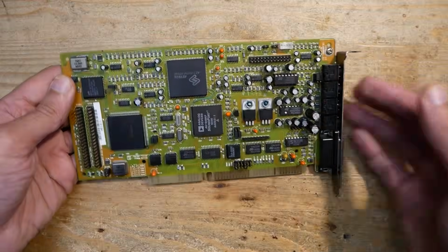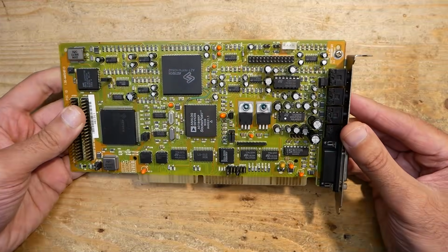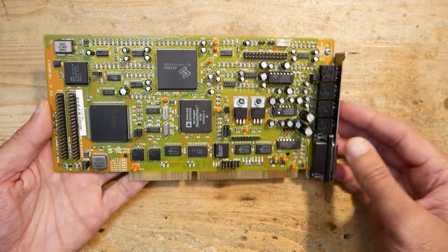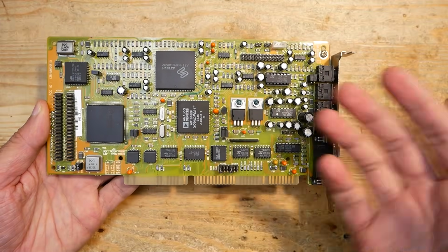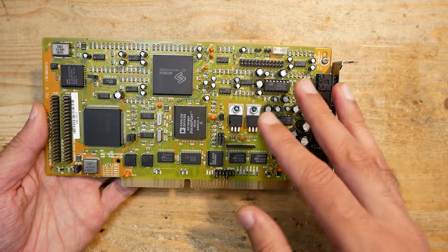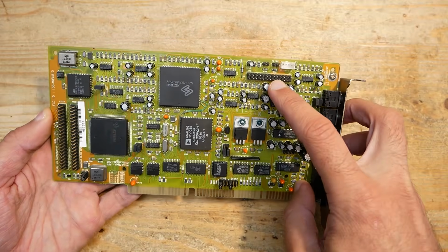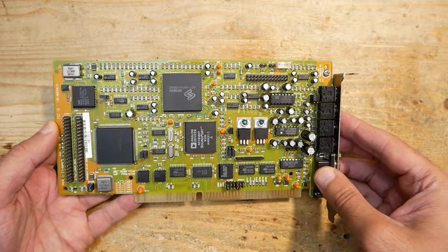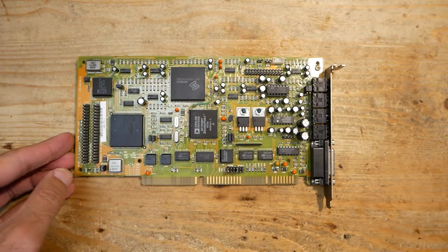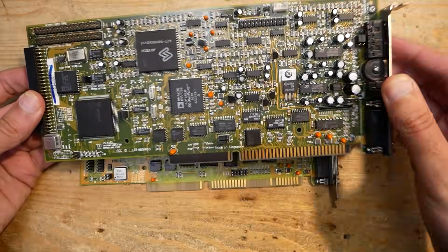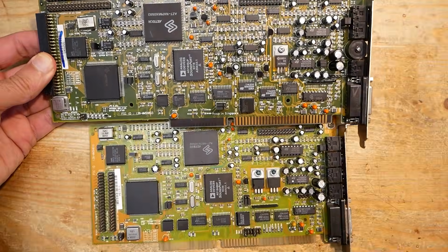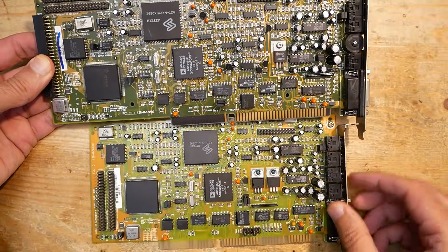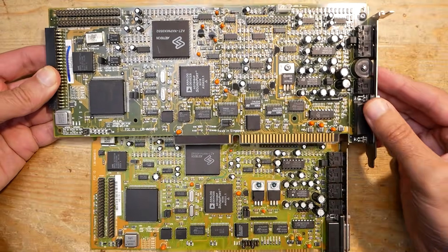So, as I said in the last video, the Sound Galaxy Basic 16 doesn't have MPU 401 support, so this card is not able to provide general MIDI sound, and although it has a wavetable header, it's kind of useless in DOS games. Or is it? The NX Pro 16 is basically the same card, with same chips, so it shouldn't have MPU 401 either, and I confirmed it with some tests.